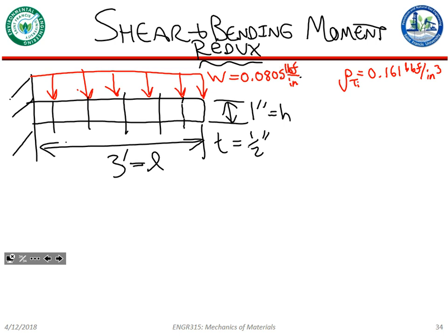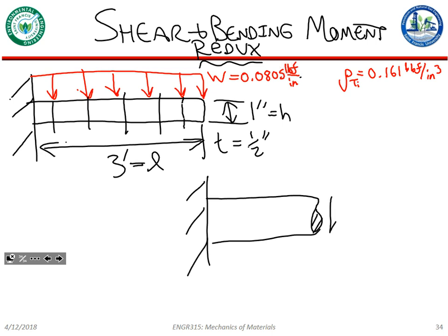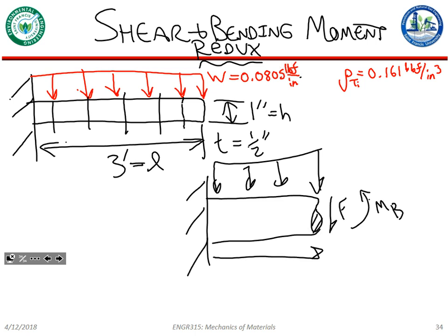If I take a cross section, I have shear force and bending moment, and I need to know all the loads acting on this particular section. If I have some load distribution characterized by pounds per length, force per length, and I know what this length is, I can find a load. So that's why we care about it in the long direction.